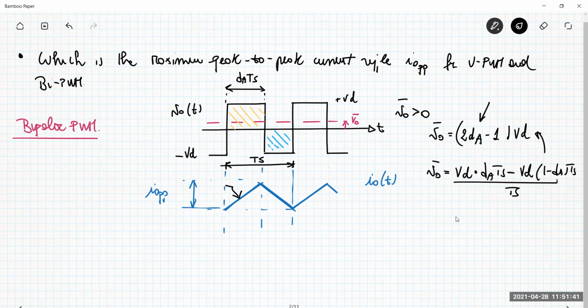In order to find the AC component of this current, we have to consider the AC circuit. We can obtain it by replacing the 4-quadrant converter by a voltage, which is just the AC contribution of the output. We can use the inductance. Let me skip the resistance for a moment, as we did for the example in the 2-quadrant converter.